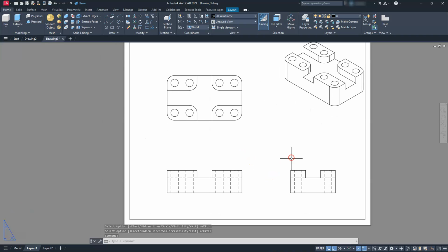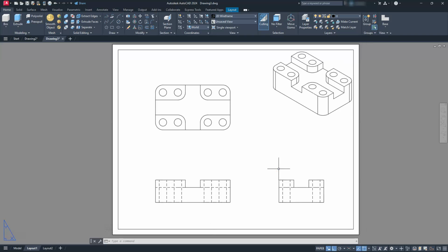Okay. Let's go ahead and put our center marks on here next. So we can create a center layer, or we don't have to. And if you want to see me create center layers and all of that stuff, I would refer that you go back to that 2D drafting video. But in this one, I'll just make it really super quick because I'm kind of looking at the time of this video. So let's go ahead and give you the rough version going through it, right? So if I go to the center, I'm just going to give it an extension of, no, I can't do 3 here because it's in paper space. I can actually leave it at 0.12. Let's go ahead and leave it there and see what happens.